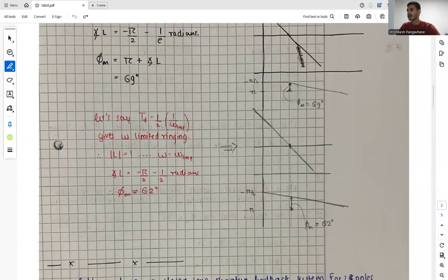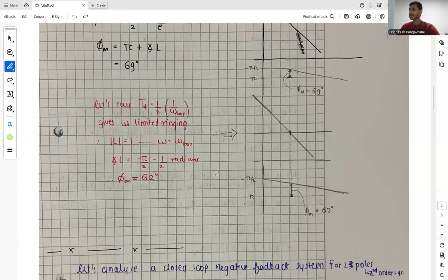So again the ramp will be decreasing with minus 20 dB per decade, and at the point of omega loop, the phase will also be lagging likewise, but the phase difference from minus pi to the actual phase comes out to be a phase margin of 62 degrees. So this states that a system with a phase margin of about 60 to 70 degrees is safe to go.